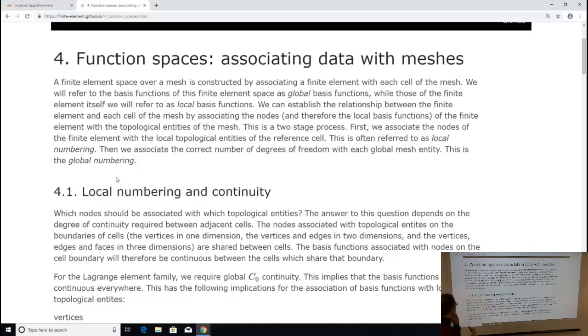The reason we need that is because when we do continuity, which you guys have done and we will revisit in a second, we need it to be the case that those basis functions which are associated with the surface of the element actually join up with the basis functions in the next physical element. And that will only happen if the mapping is consistent.